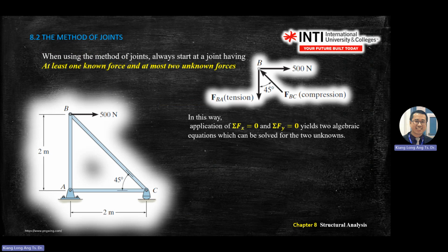Okay, so when we have all the forces equal to 0, all the Y equals 0, it means all the forces equal 0 by using the equations of equilibrium. We are now using the method of joints. In the method of joints, we focus on the pin, and we assume all the members are two-force members. All the forces equal 0 here, and you can extend to X, Y, and Z directions if it's three-dimensional. Okay, this one is 2D.